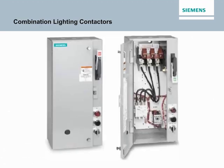Siemens combination lighting contactors provide a disconnect means for lockout and maintenance, as well as short circuit protection. Furthermore, they're UL rated as service entrance equipment, permitting equipment to be pole mounted and installed directly off utility power lines. This makes the product ideal to control lighting in remote locations such as sports facilities, parks, fairgrounds, streets, and highways. It's also ideal for industrial and general area lighting.